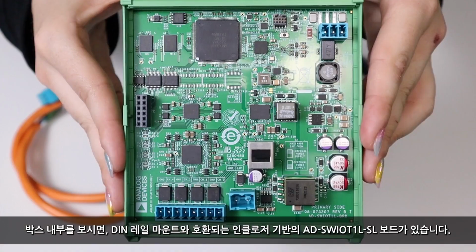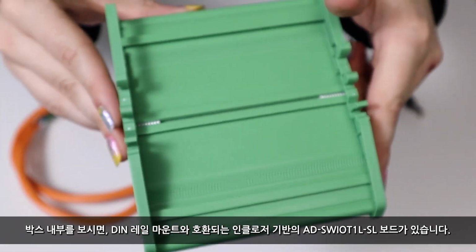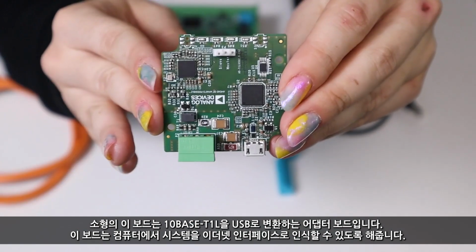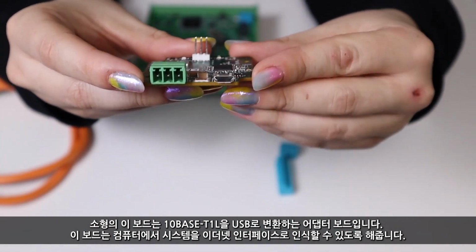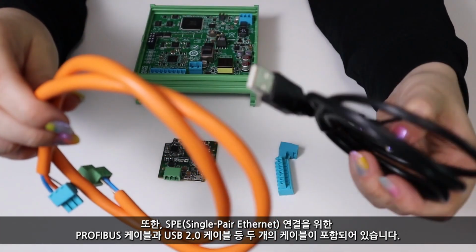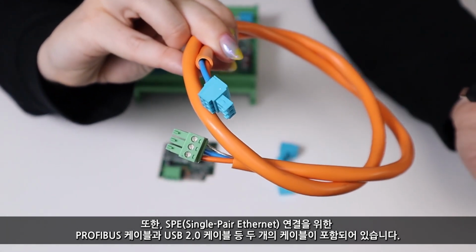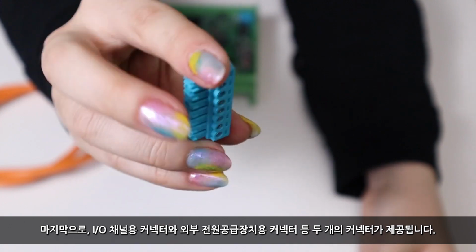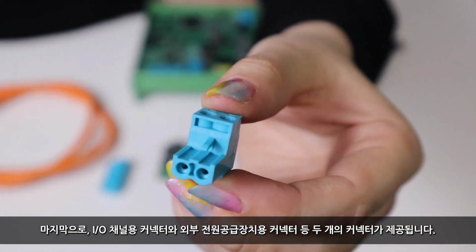Inside the box, you will find the AD-SWIOT1L-SL board in an enclosure compatible with DIN rail mounts. The smaller board is a 10-base T1L to USB adapter board. This board will expose the system as an Ethernet interface on your computer. There are 2 cables inside, one Profibus cable for single-pair Ethernet connectivity and one USB 2.0 cable. Finally, you will see 2 connectors, one for the I/O channels and one for the external power supply.